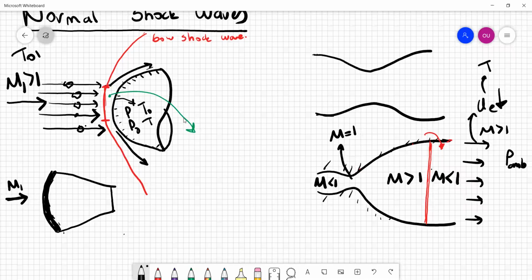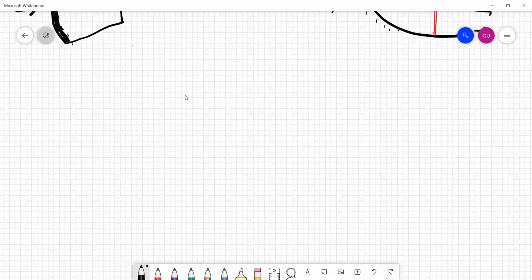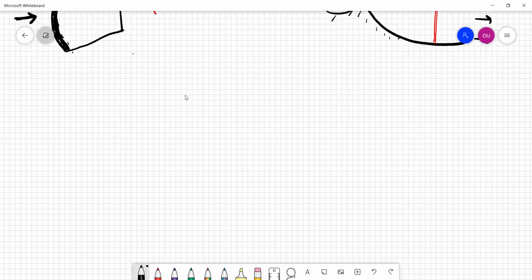So in order to find what actually happens, or what equations we can use to calculate the flow parameters occurring after the shock wave, our equations are basically known. The governing equations we have derived so far, mass, momentum, and energy conservation equations, are our starting points. We will make use of those equations to come up with what we call normal shock relations, as is known in the aerodynamics community, to be able to calculate the flow conditions after a shock wave.